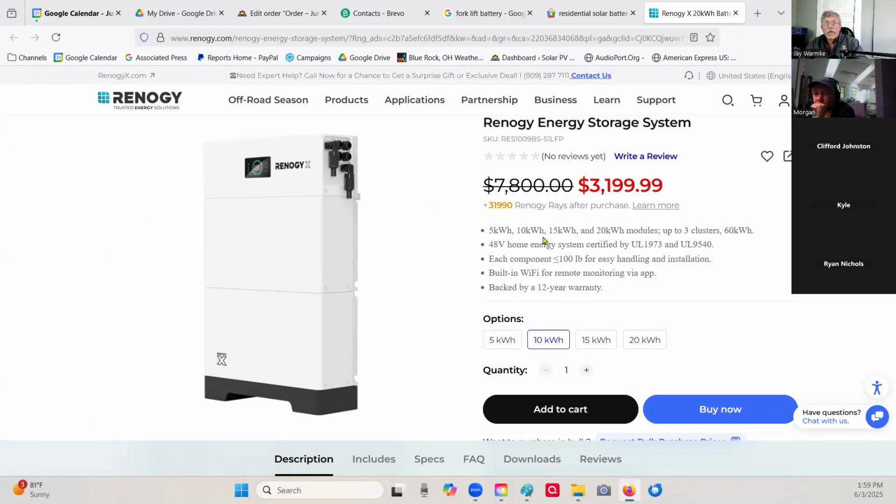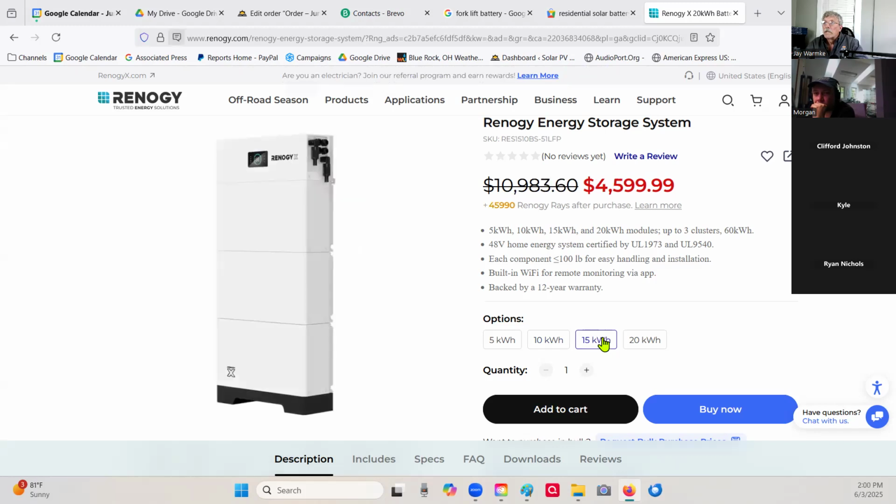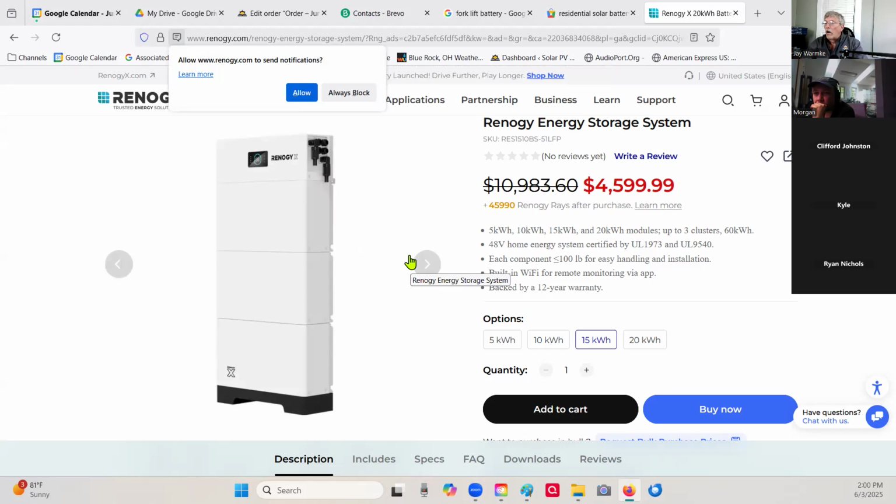Well, we'd need a 30 kW, or probably two 15 kW systems. So in this case, all of the D rate, all the depth of discharge, all of those calculations are figured in when you're doing this. So using lithium ion, I need two of these for that same situation. So it's only going to be, say, $10,000. A lot cheaper than the lead acid.